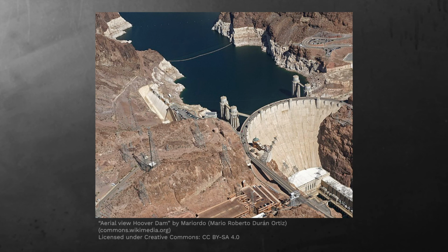It's called an arch not because it has the structure of an arch that we're familiar with from architecture resisting gravity. In this case, the arch is horizontal. And we make it horizontal because we're resisting a lot of hydrostatic loads. We have to take those forces and put them into the rock on the side of the canyon that can resist the loads. So here's a perfect example of when we would take a curved surface and have to calculate the equivalent hydrostatic forces.